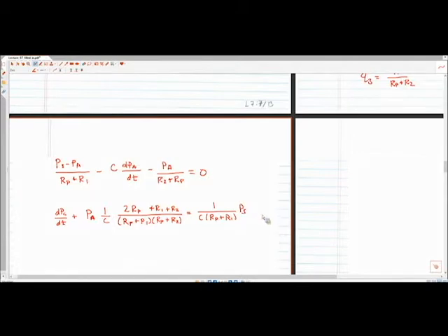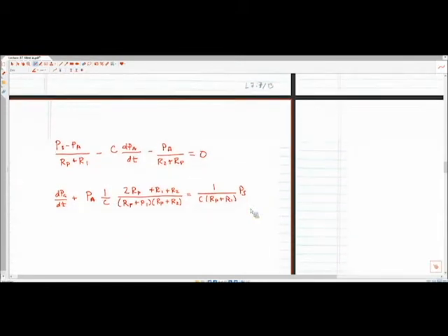So here what we have is a differential equation. What we've taken is some configuration of a fluidic system, trying to understand this from an electrical circuit analogy. And here we get a first order differential equation, and it's a non-homogeneous differential equation, right? So we have a non-homogeneous term driving the system. In a form that looks a little more like what you may have seen before, we would have the differential equation dPA/dt is equal to minus 1 over tau, which is the time constant of the system, PA plus K PS, right? That would be the more standard form you'd see, maybe for a differential equations course.